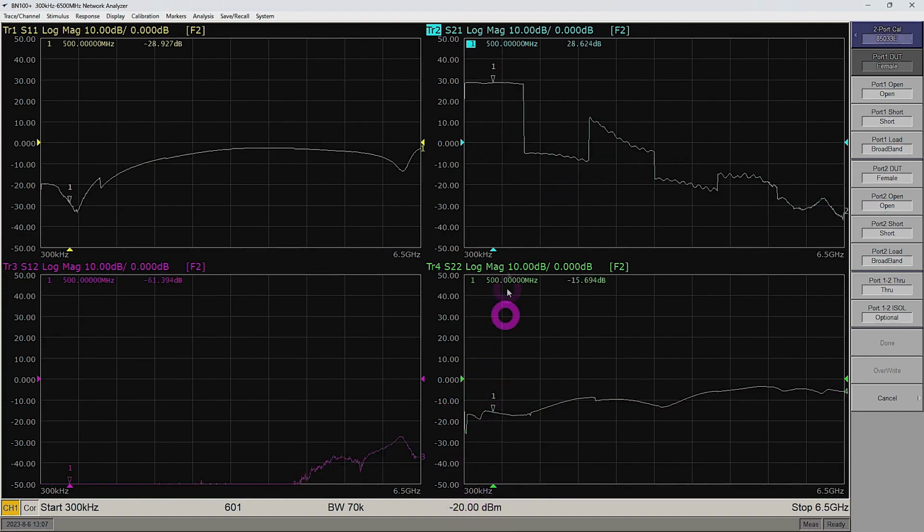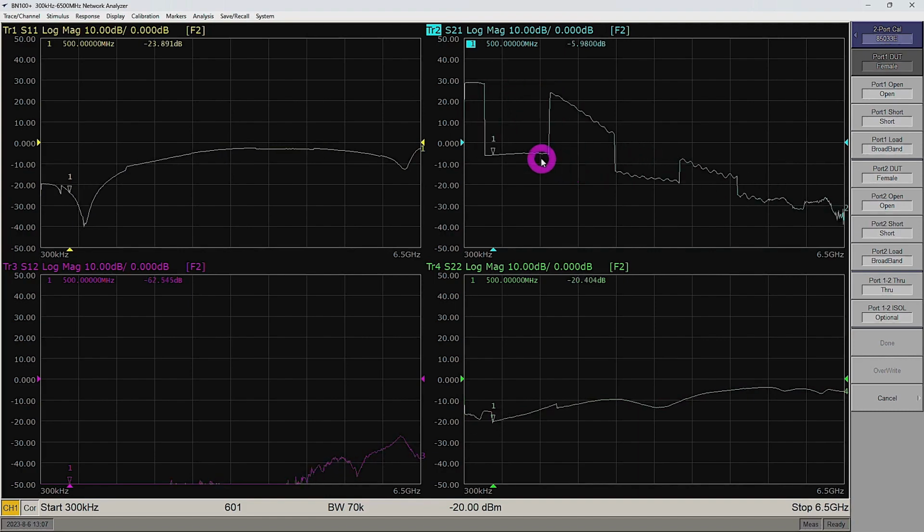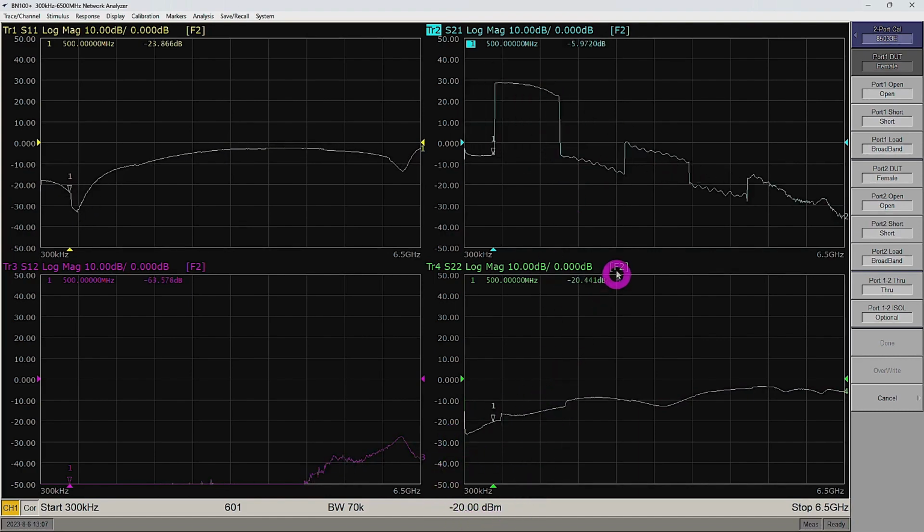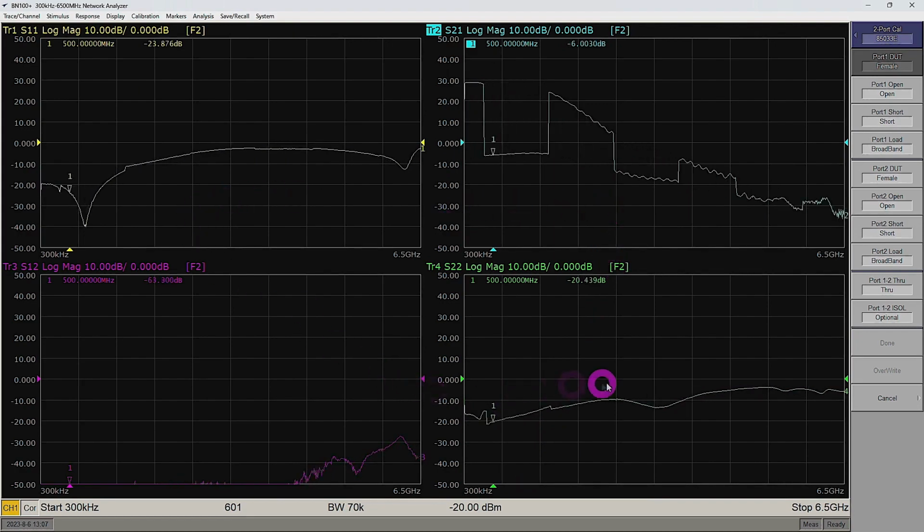So -20 dBm with about 30 dB of gain is +10 dBm. It's getting close to the saturation of this amplifier. But unfortunately I cannot go below -20. You would need an external attenuator on top of that. Everything else doesn't seem to change much.